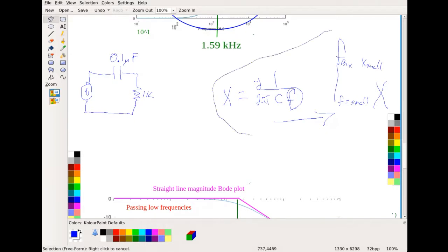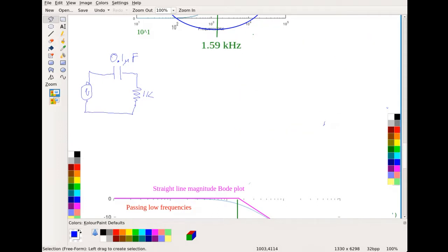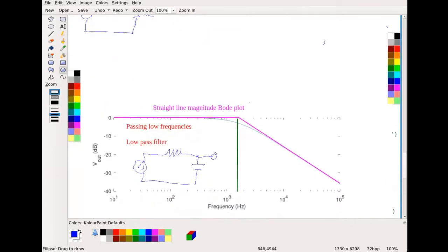What happens is, for this right here, at low frequencies, this doesn't drop much voltage, so therefore the voltage is just passed, and this is dropping all the voltage. But at high frequencies, if I scroll down here and look at that circuit I just put in, this acts like a short, and so it's basically shorted to ground at high frequencies.